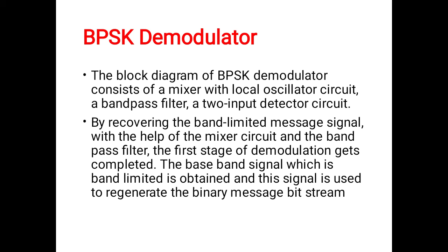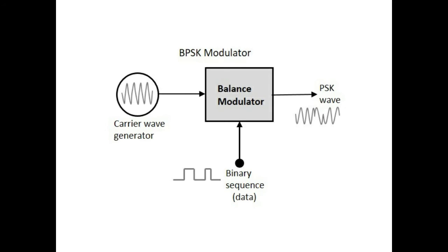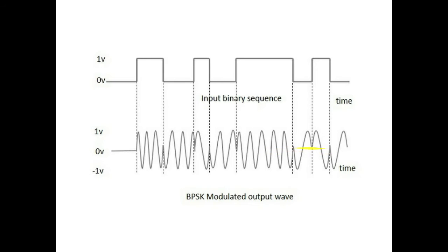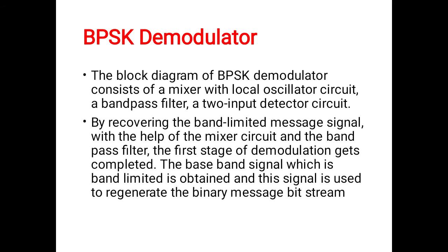Now BPSK demodulator. Here there are a few differences. It will have a mixer with a local oscillator circuit and a filter, along with that a 2-input detector circuit.